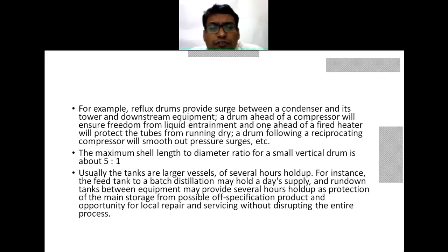For instance, the feed tank of a batch distillation may hold a day's supply, and rundown tanks between the equipment may provide several hours hold up as the protection of the main storage from possible off specification product and the opportunity for local repair and servicing without disturbing the entire process.